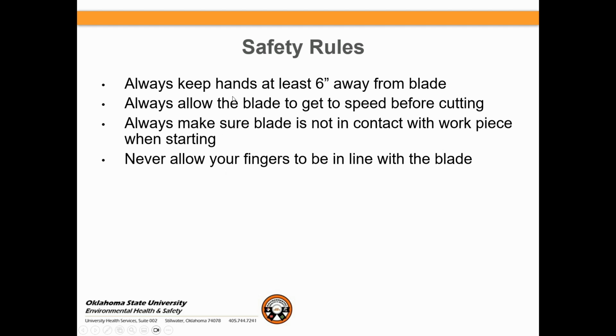Always keep your hands at least 6 inches away from the blade. Always allow the blade to get to speed before cutting. Always make sure that the blade is not in contact with the workpiece when starting, and never allow your fingers to be in line with the blade. Keep your hands away from the cutting area as much as you possibly can.